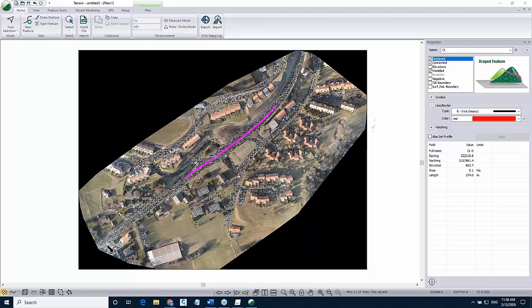Sounds good. I think we're down to two more questions, and we'll just see if there's any more. The next question is, can you save surface data from Terrain and then import it into other software like Esri or AutoCAD? Yeah, absolutely. The terrain model is able to export files into different formats like LandXML, shape files, or DWG files. So when we import different LiDAR data, like here, we could export these points in a different format and use it in other software.